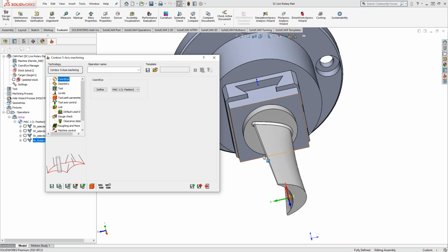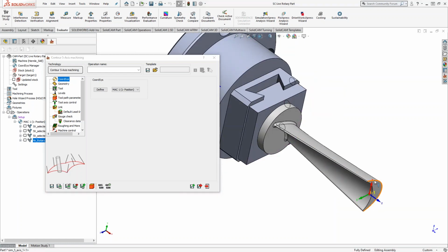So let's say on a part, you have it set to do a particular angle relative to the rotary axis, maybe 90 degrees so that it's pointing down. Maybe you want to shift it in the Y direction a little bit. But as it goes along, there might be a pocket or a feature on the solid or even the fixture itself where the tool just needs to tilt right at that instant. Well, if you set a series of tilt lines along the part and then just the last one cocked at a certain angle so that it actually avoids that gouge, that's what this would allow you to do. You can really control point by point the angle of the tool.